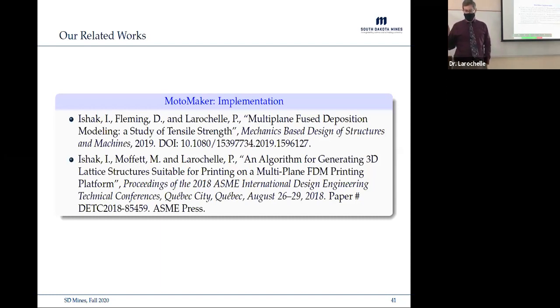Printing resolution is determined by the repeatability of the robot arm and the robot arm controller system, which on this system was plus or minus 2/1000 of an inch, guaranteed within 6-dimensional space. Most of the workspace is like an order of magnitude smaller than that, but that's what's guaranteed.